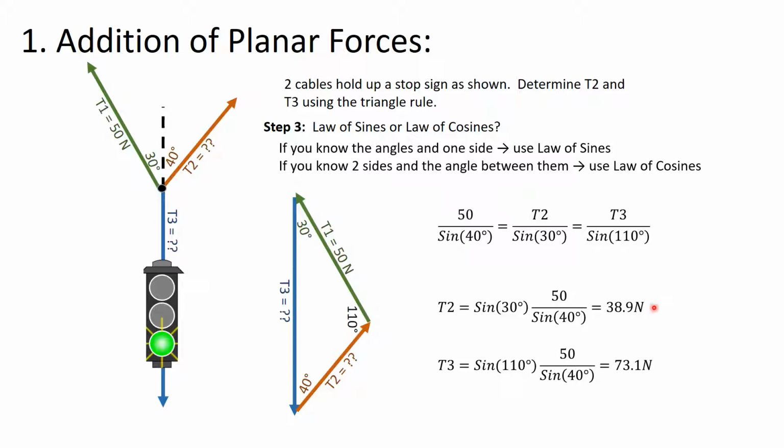for the tension in this cable here and T3. Notice we have newtons labeled on here, and as well as the magnitude, we should also be paying attention to what angles these are happening at. So 40 degrees plus 50 degrees, so this is going to be coming up at 50 degrees. And then T3, of course, is all in the y direction.